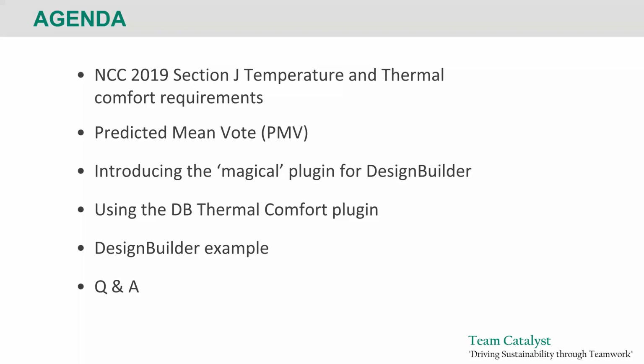Right, so today's agenda is we'll review the temperature criteria and the thermal comfort criteria that have been put out in the new National Construction Code. Then we'll look at what exactly is predicted mean vote, or PMV, as it's known in its short form.